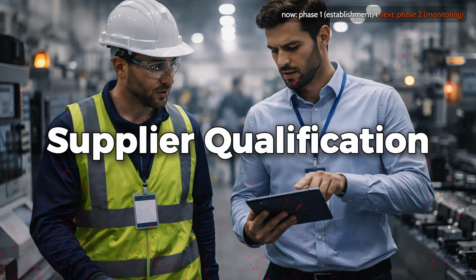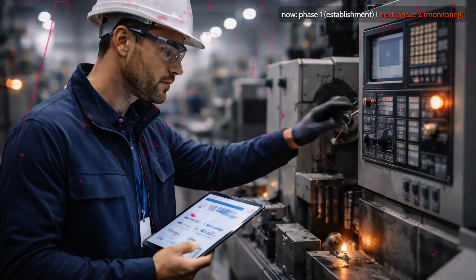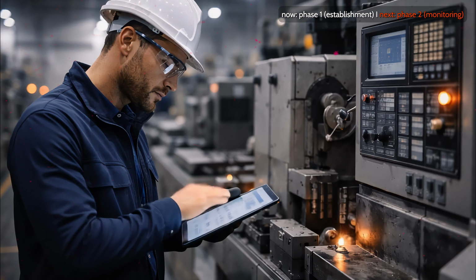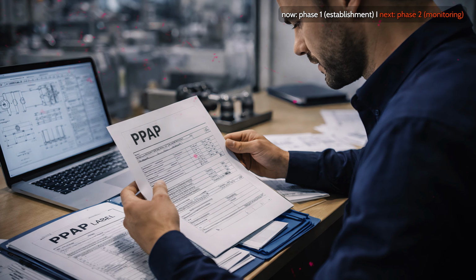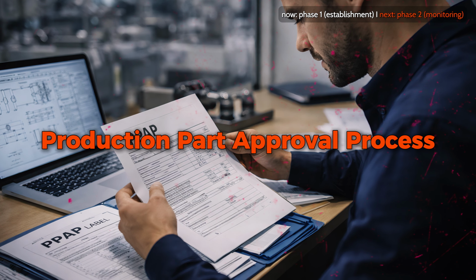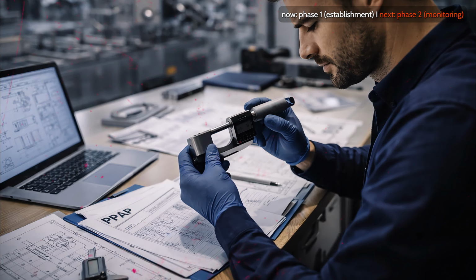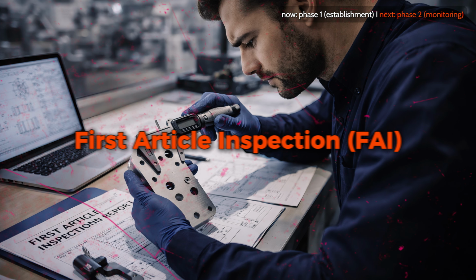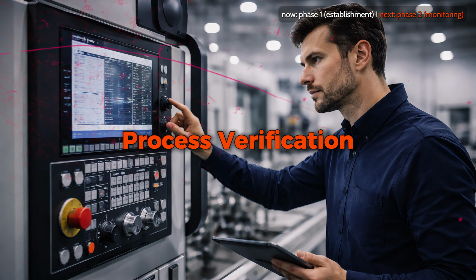Once the supplier is verified, the next step is qualification. Qualification often starts during on-site audits, where you assess process readiness and capability. The most common approach is PPAP, Production Part Approval Process. PPAP uses representative parts and supporting documentation to confirm that the process is stable and repeatable. This includes first article inspection, sample validation, documentation review, and process verification.